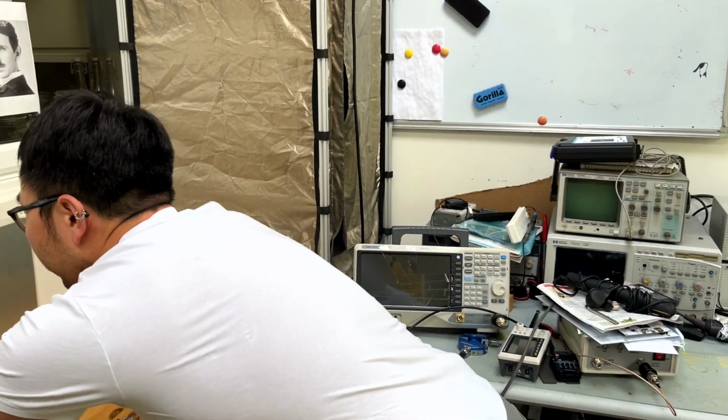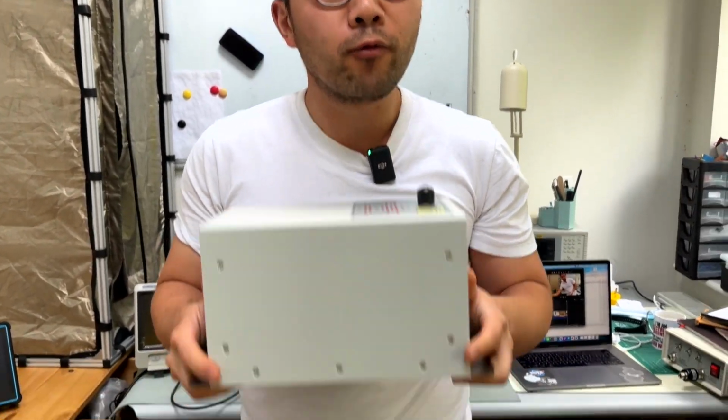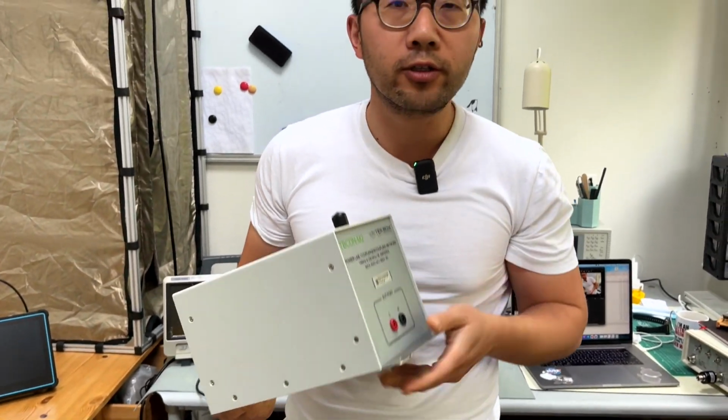CDN stands for coupling decoupling network, and it provides a constant impedance. And when I say constant impedance, I mean the constant common mode impedance. The standard defines that impedance level at 150 ohms. What does that mean? It means between 150 kilohertz all the way to 80 megahertz, the CDN, such as this one, provides a constant common mode impedance of 150 ohms to the product under test. Now you may ask, why do we need 150 ohms? Where does that number come from?